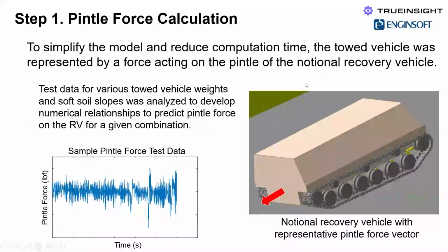Okay. So in the pintle force calculation, here on the lower left, we see some sample test data of the pintle force. And as seen on the lower right, we're going to apply that pintle force on the rear. And actually, in this concept we're looking at, there are 2 attachment points, and so we distribute the load on those 2 points in the back of the vehicle.